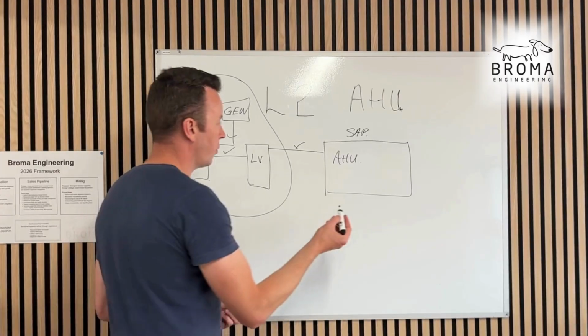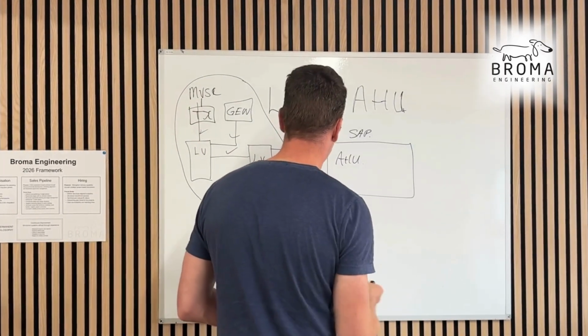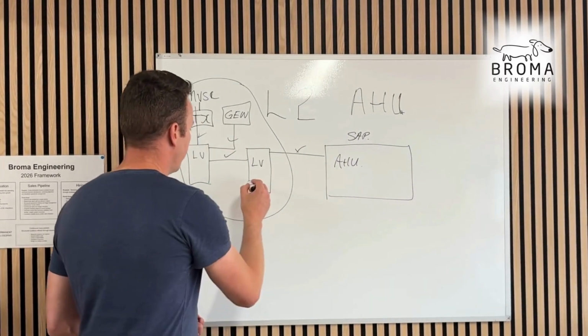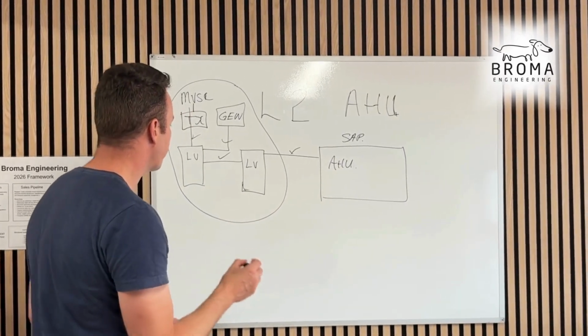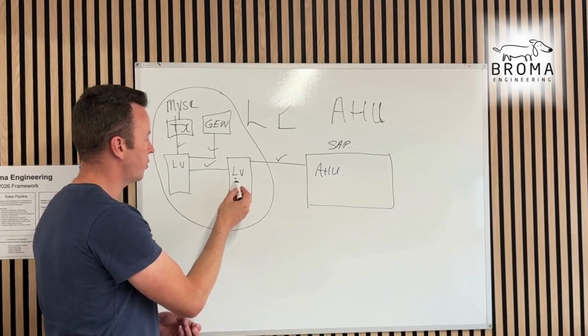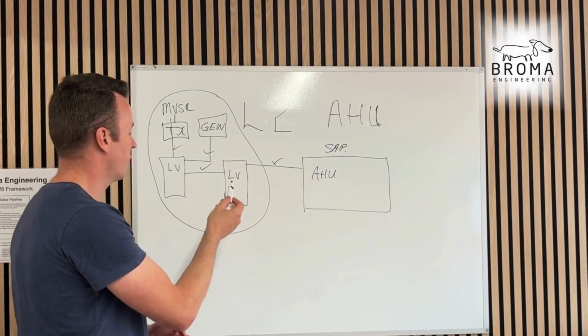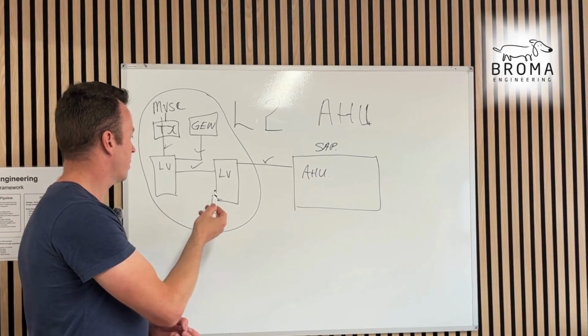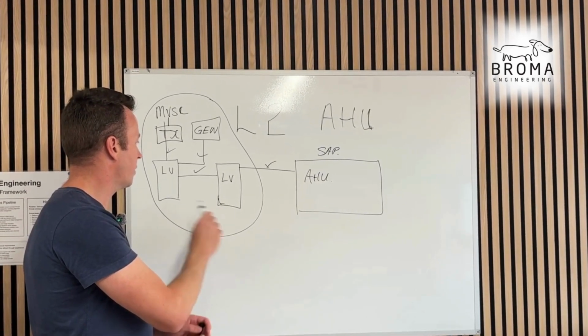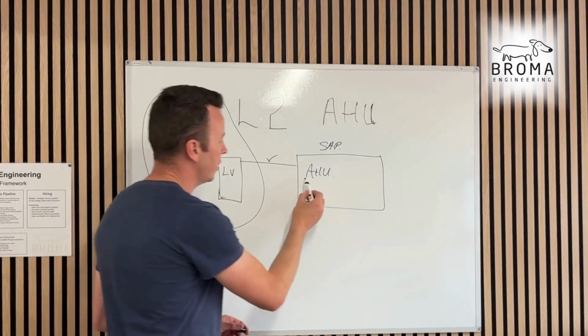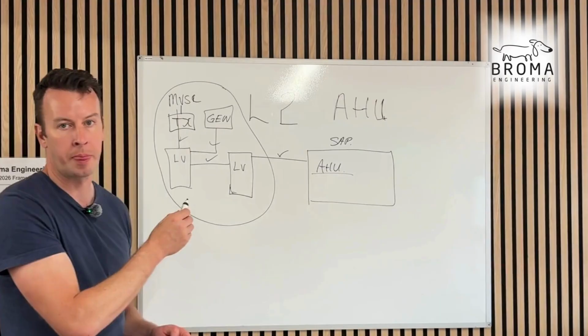So on the pipework, if it's high pressure, sometimes it's just easier to have it locked. If it's very low pressure, maybe there's no need. So LV switchgear upstream, all needs to be done, all needs to be tagged, and yellow tagged, everything done. So you could be waiting here if there's problems upstream.